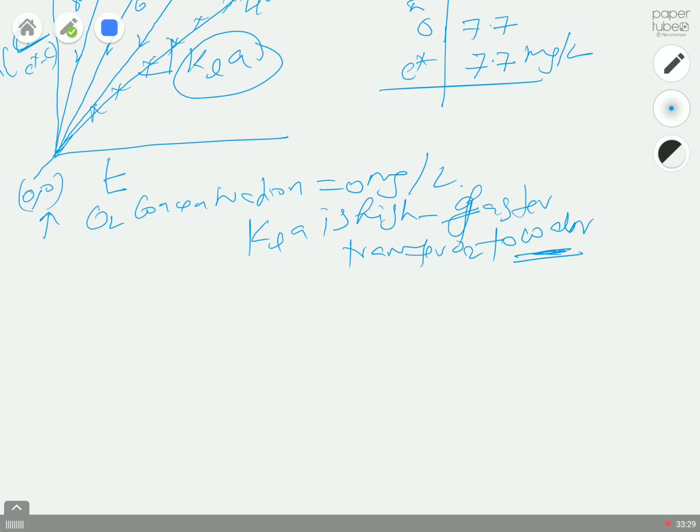By the way, I forgot to mention how we do the experiment in the lab. You pass nitrogen gas, which knocks out the moles of oxygen and carries them out as air, and then you supply pure oxygen, collect the experimental data, and calculate the mass transfer coefficient.